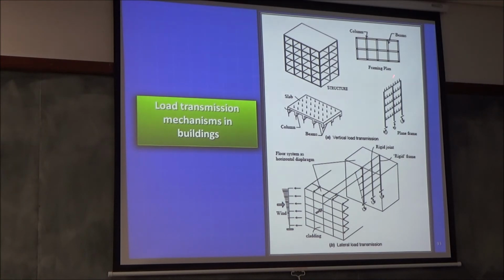Similarly, you have a rigid diaphragm here, which is what connects all the 5 frames and makes sure they displace more or less the same. If you have a stiff diaphragm, then it ensures that the whole thing moves like a rigid body. It could twist, but it will again twist like a rigid body. If you have a flexible diaphragm, it's going to deform such that when the wind is acting, the middle region will move more than the end regions.